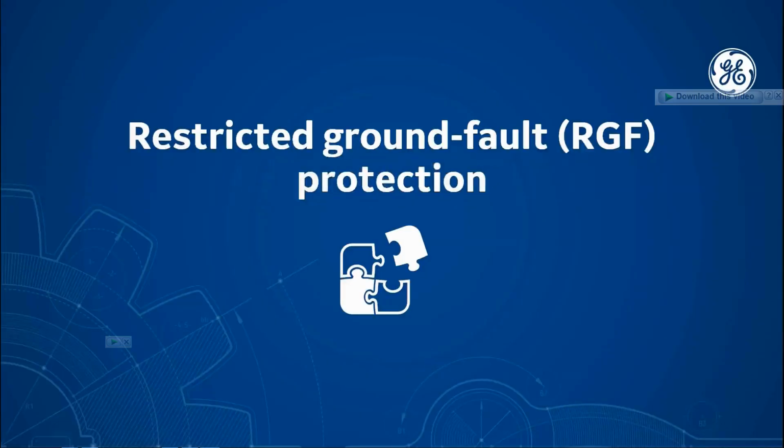For small fault currents, primarily faults close to the neutral or star point of a Y-connected winding, the phase CT-based 87S is not sufficiently sensitive. The solution is to use the restricted ground fault RGF element, also known as the restricted earth fault element. The word restricted means focused on the area of the generator windings within the boundaries of the CTs. This protection method is fully capable of service. This protection is used mainly for small generators where the ground differential protection is not possible.